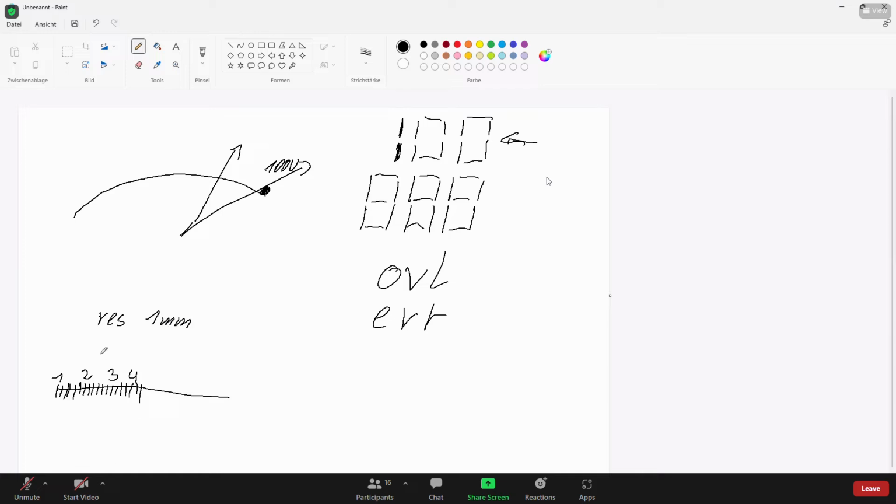But when you cut, for example, your linear at this point, you would have an error of 2 centimeters. That's the error. The resolution is still 1 millimeter. That means the error can be much bigger than a resolution, but the error cannot be smaller than a resolution.